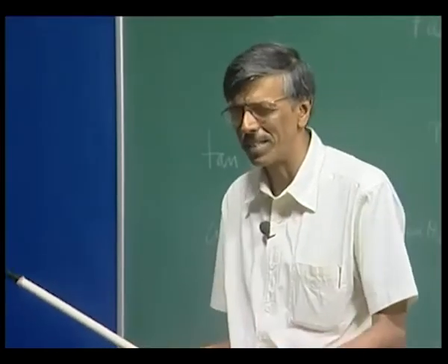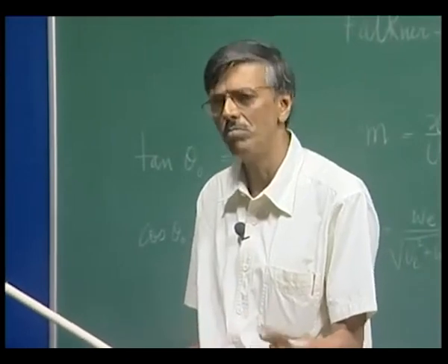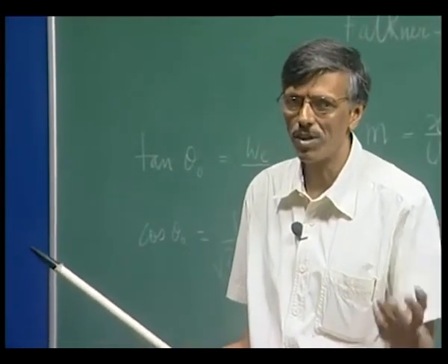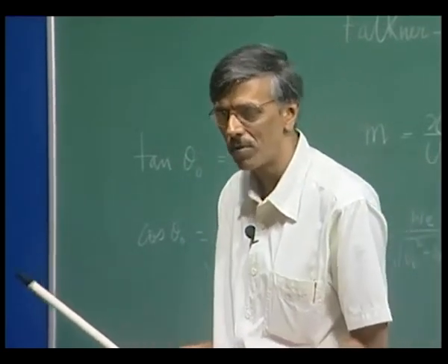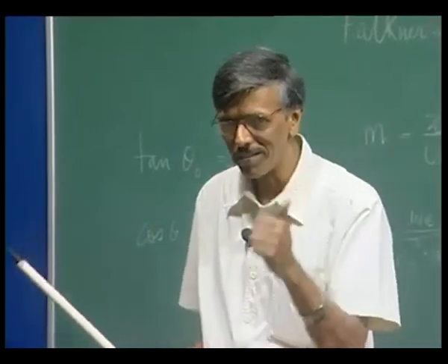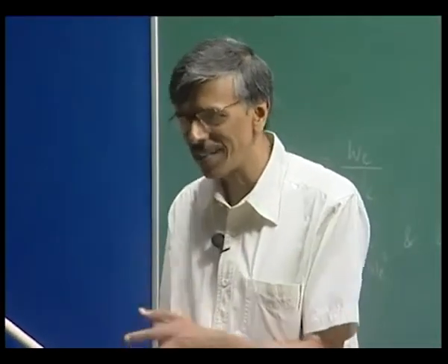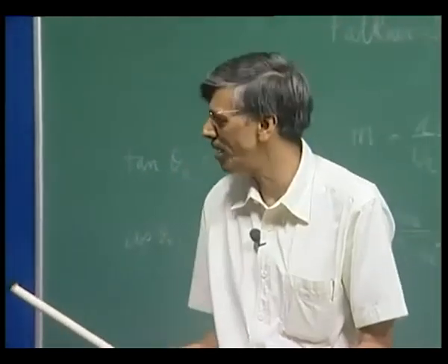There are other mathematical issues, that vortical field also happens to be divergence free, because it is a two dimensional flow. So, it becomes automatically divergence free. Why? Because omega is in the z direction, divergence of omega in the xy plane is of course 0, because omega is not a function of z.